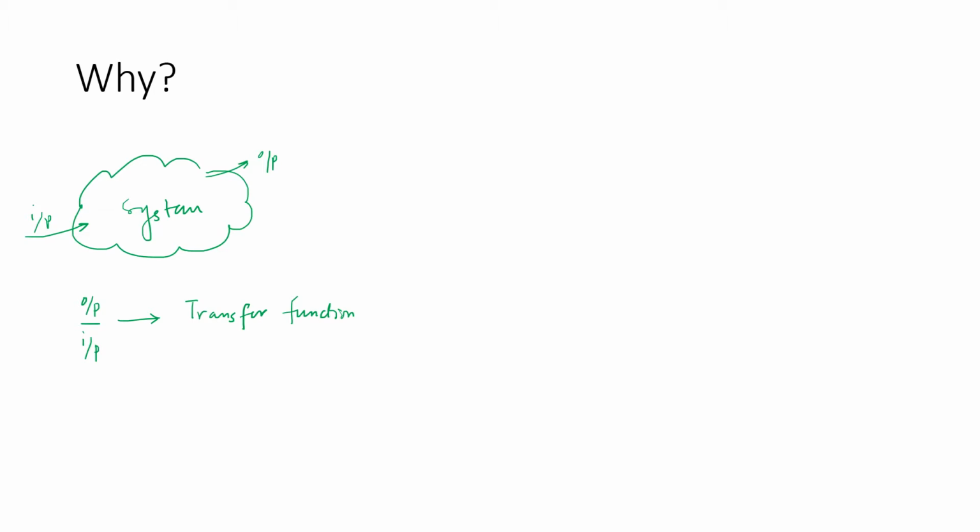For example, it is going to give you the characteristic equation that we can plot on an S-plane. This S-plane is going to have the real axis and the imaginary axis. And if we place poles over it, we are going to have a commentary on the stability of the system and the behavior of the system if certain parameter is changed.